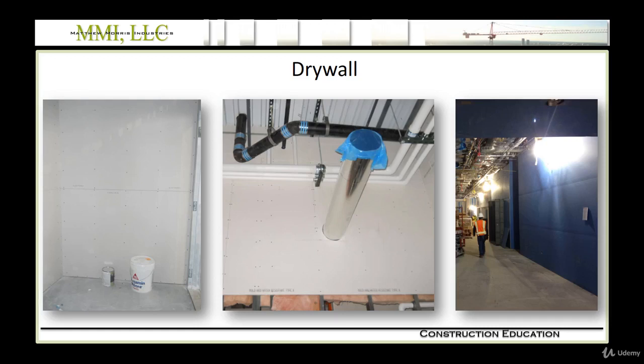I mentioned earlier priority walls. So sometimes we install all the studs, then we install drywall at the top of the partition, and we fully finish it before we have any in-wall rough. And we do that usually on the corridor side of the wall, like you see here, because we eventually have to run MEP systems really tight to the wall.